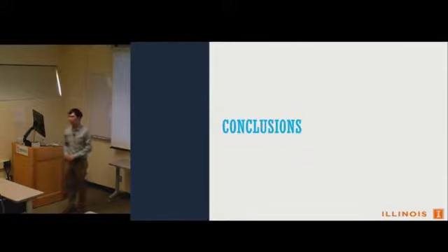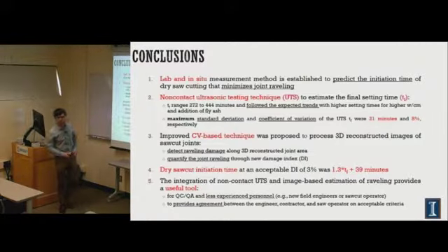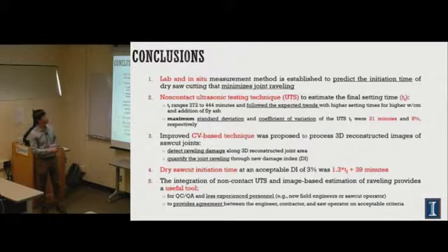Any other questions? So I would jump to the conclusion of this. What I found is I made a lab and in-situ measurement method to predict the initial time of the dry saw cut. You can see the dry saw cut, not the wet one, to minimize the joint raveling. And the ultrasonic here, I found, can estimate the final setting times.